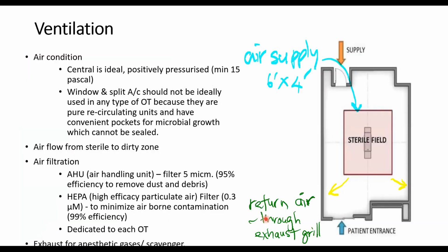The air conditioning ideally should be centralized, which gives positive pressure of a minimum of 15 Pascal into the operating theater. Window or split aircon should not be used.